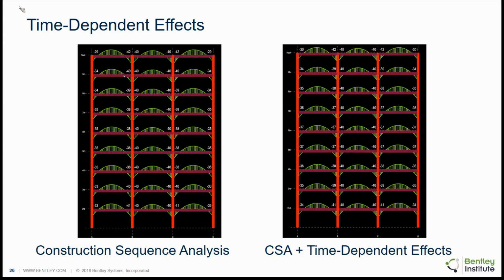One thing I didn't point out is I set up those stages, but I could have set up one more stage and indicated that it was out at some time, say 5 years from now, and then I could actually have used those results of the creep and shrinkage and concrete strengthening that had occurred over the next 5 or 10 years and looked at those effects.